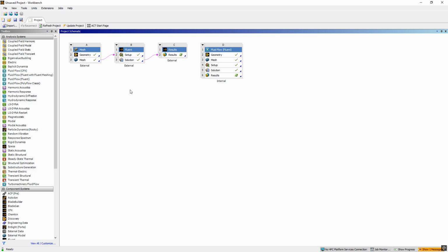And that is the important part of CFD, because the most difficult part, the real part, is to be able to select the correct things, make sure that you enter the correct values, make sure that you put in the correct variables, and also at the end being able to make comments on your results, being able to understand if your result is correct or not, being able to come to the conclusion that the obtained result is acceptable, or what is wrong with that result. If you have a problem, is it because of your geometry? Is it because of your mesh? Is it because of your solution? Is it because you selected the wrong viscosity model, for example?